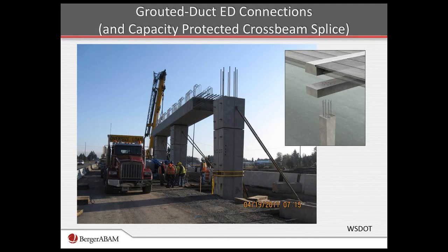We wanted the gravity load of the cap beam to be controlled, statically determinate as you place it. It also helped us save weight of that cap beam. You've got a splice in the center with a lot of bars, again, minding the detailing. This went together quite well, but it does require careful attention to detail.